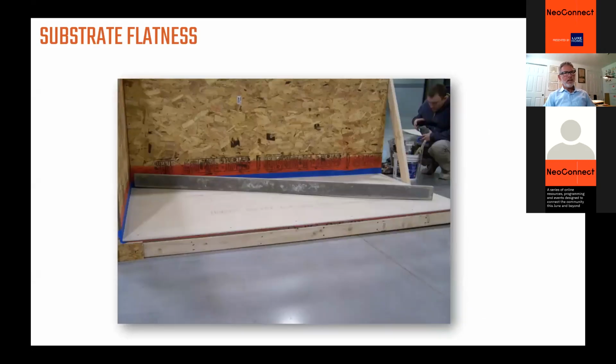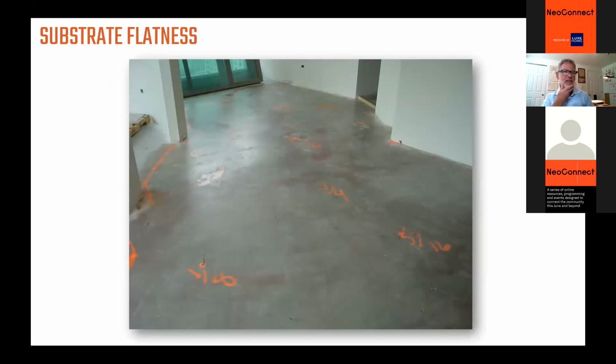So this is taken in our training center. This is a mock-up that our tile instructors have built, and they've intentionally built it out of flat so that the tilers get experience in evaluating and assessing floors that they are to lay tile on. So this would not be an acceptable substrate.